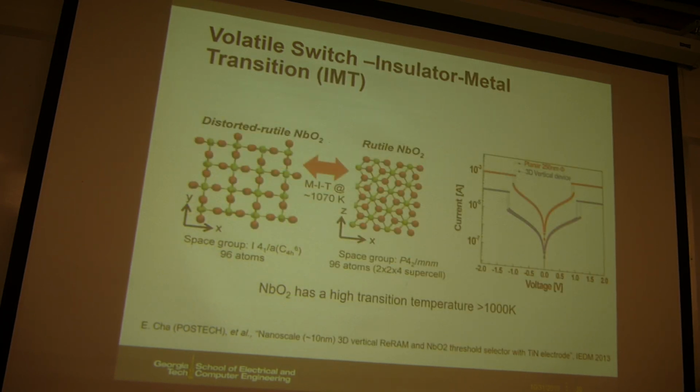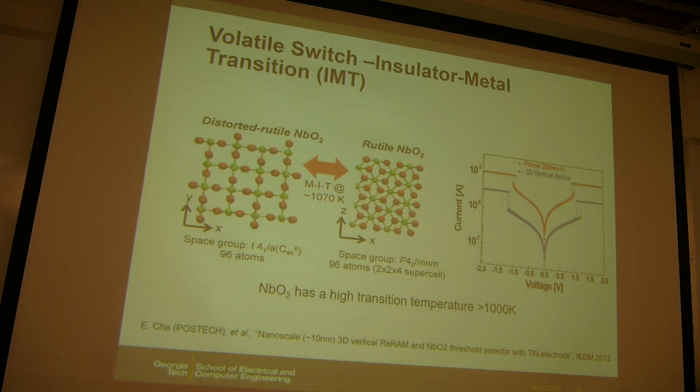And there is some other research going on, like niobium oxide. Even in my research group, I have done this. This is based on this material, and this material can show this kind of abrupt switching beyond some threshold voltage. However, the challenge here is the on-off ratio is not very large. It's only like 100. The on-off ratio, let's say this is nonlinearity, how large you need depends on how large a memory array you are building. So the larger the array size, of course, you want higher nonlinearity.